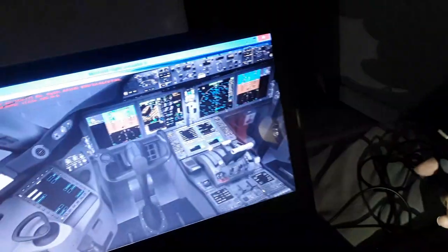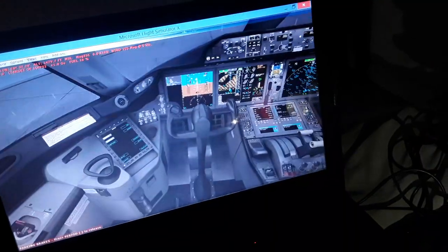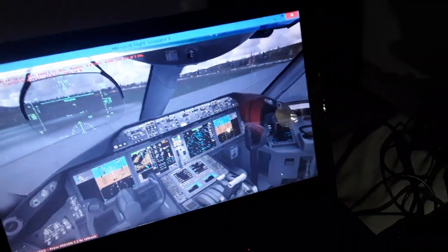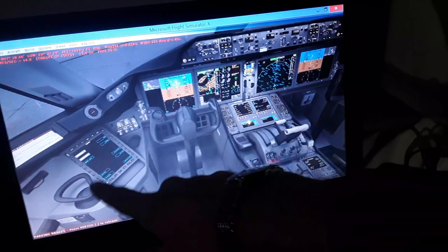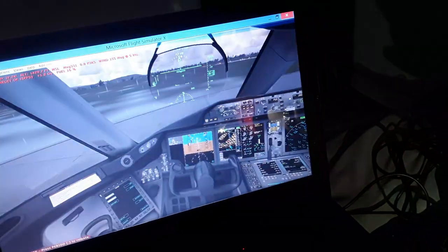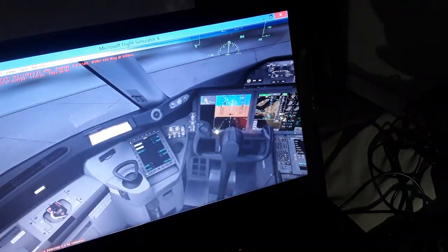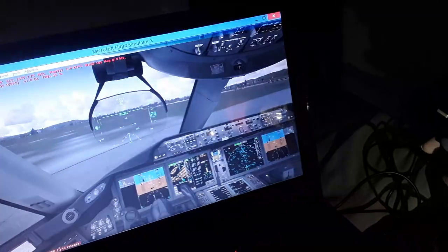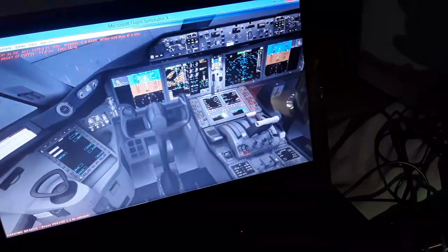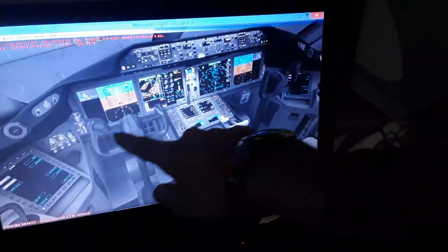You have also the rudder pedals. You control the vertical tail, the rudder, at about 45 knots or higher in takeoff. You have also the nose wheel steering. The tiller 76 degrees decreases to like 7 degrees at 40 knots, then all the way up to 70 knots it goes to 0, and then you have the rudder pedals for making directional turns on the ground. You have also the toe brakes in the rudder pedals, so you have a lot of controls over here.